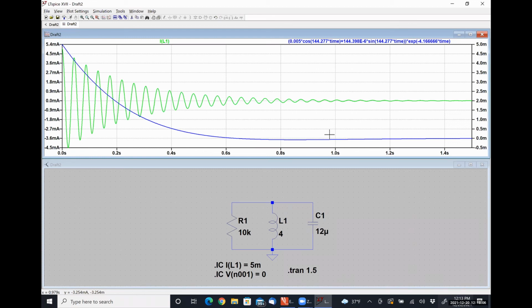As I pointed out a couple of minutes ago, it is imperative that you make sure the scale on the right-hand side for your mathematical expression is the same as the scale on the left-hand side for your simulation, so that you're actually comparing apples to apples. And that's another place where you can be doing everything perfectly right, but the scales make it seem like you've made a mistake, okay? For this particular problem, we could fix that by just putting units of amps here, and it would work itself out.